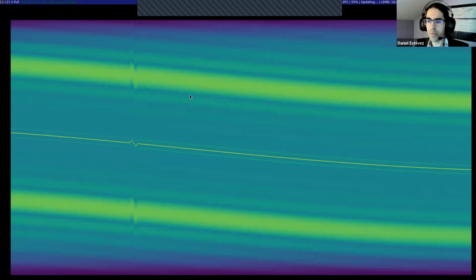By the way, I should also mention that, as often happens, people have found shortcuts to decoding the signal. Especially the recording from GBT has such a great SNR, meaning the signal is very strong because GBT is a very large telescope, that it's not necessary to lock to this carrier. You can just look at any one of these data side lobes. Of course, by doing that, you lose 50% of your signal power because by looking to this carrier, you manage to combine the information in the two, which is the same, really.